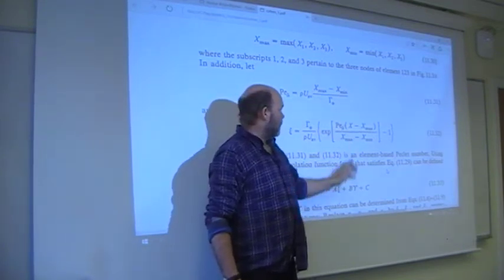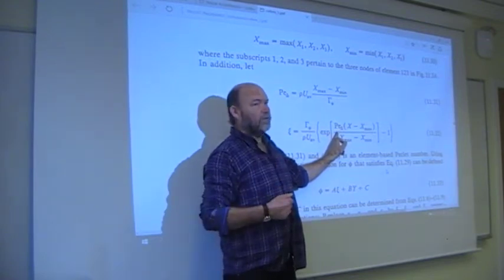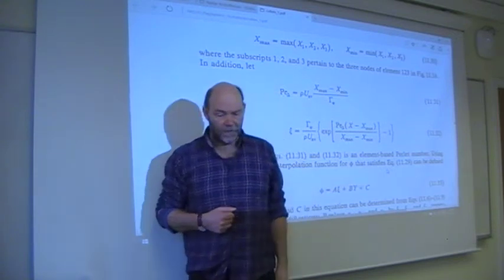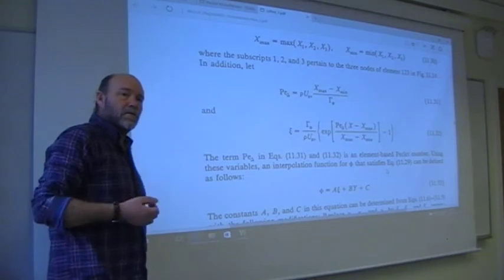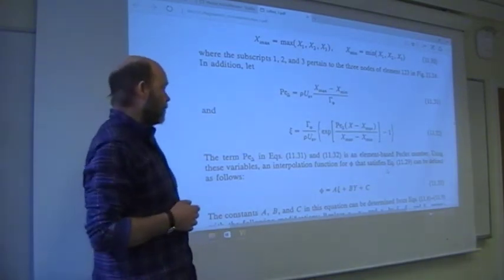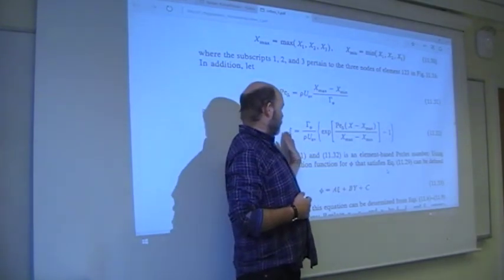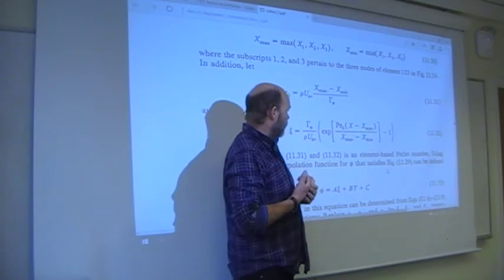As we know, this one then has to be smaller or equal to 2, or else it blows up. Not because of any instability with respect to time, but with respect to space. That's a requirement for space resolution. And here it will be sort of hidden automatically inside your grid systems.